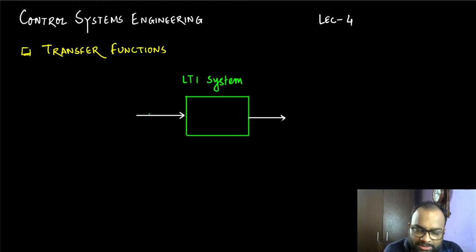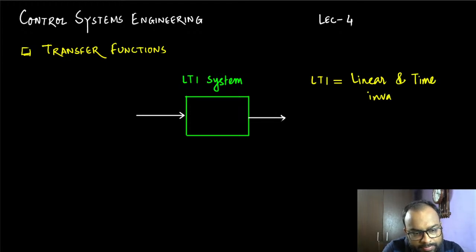So LTI systems is the thing that we need to think about. So if I have an LTI system or a system that can be considered to be an LTI system, then it's good for us. We can actually work using the transfer function model. But there are certain caveats of the transfer function model which we shall come to discussing later. Okay. So LTI, of course, in case you didn't know already, LTI stands for linear and time invariant system.